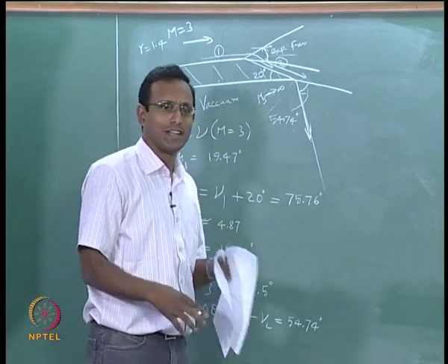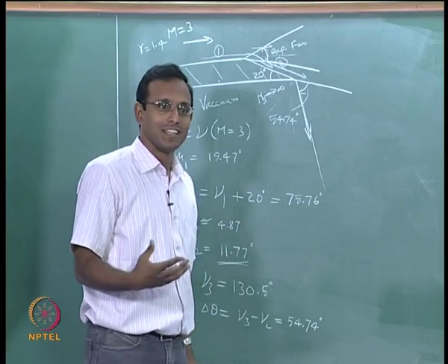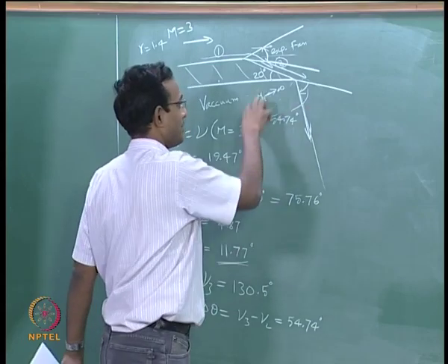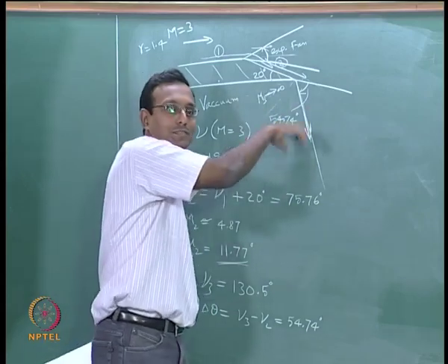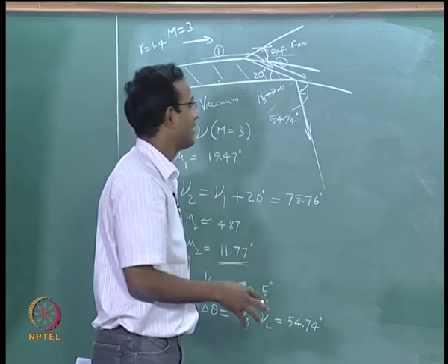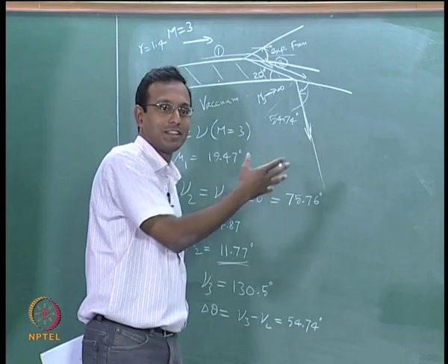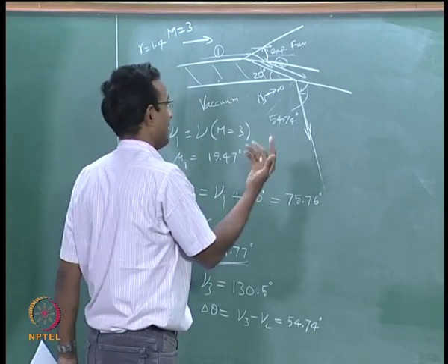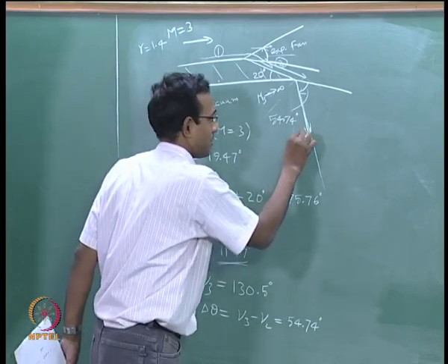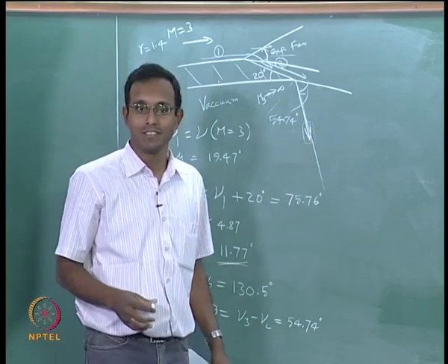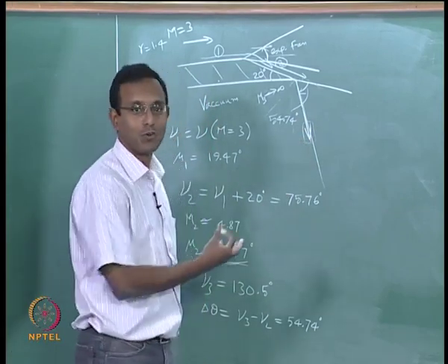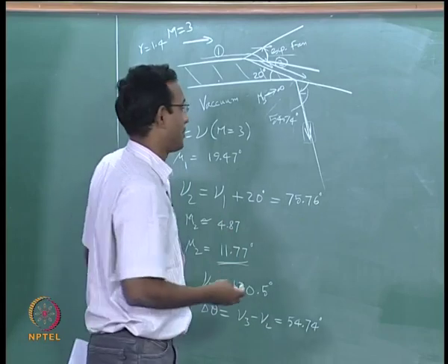We already told you that M tends to infinity is not a real situation. By then my continuum assumption breaks down, so I cannot be using this analysis here. By here pressure is 0 here and non-zero here, that situation will never arise. And at this particular situation where pressure is close to 0, I cannot apply continuum anymore. It is no more continuum, there is no molecule there, cannot be continuum ever.